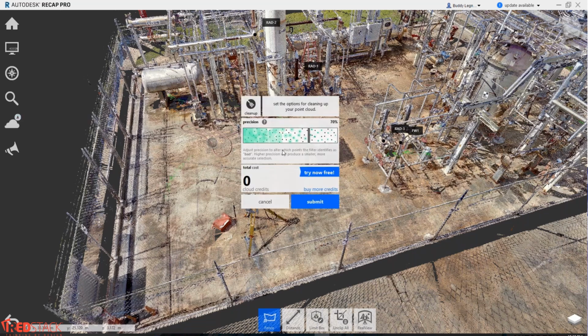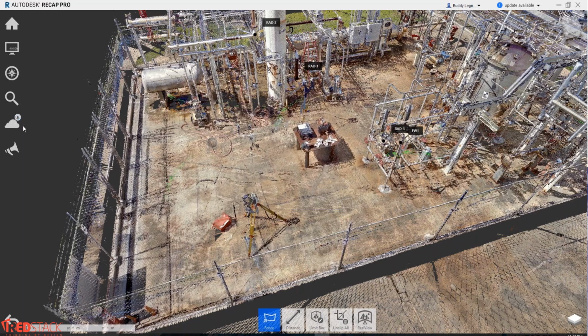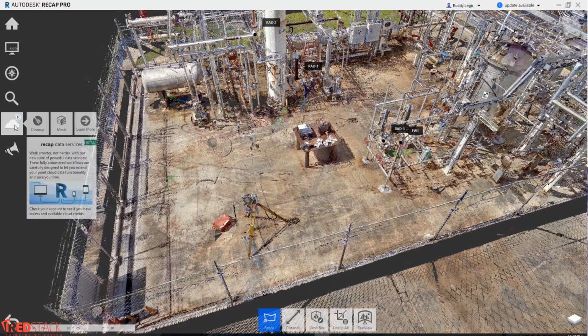And you just click the button and scroll left and right. If you scroll right, it's more. If you want less, you go left. So you don't have to do all the cleanup manually, especially when you have a massive scan data set in the hundreds and you want to do some cleanup automation.